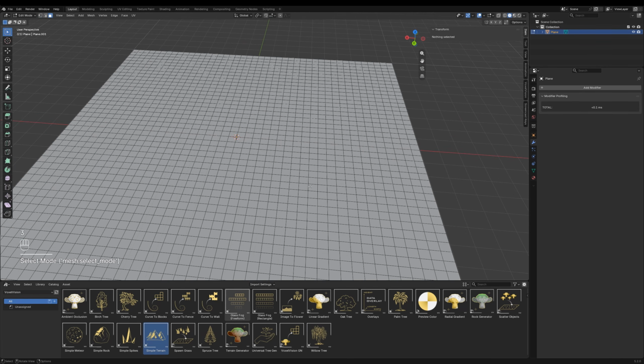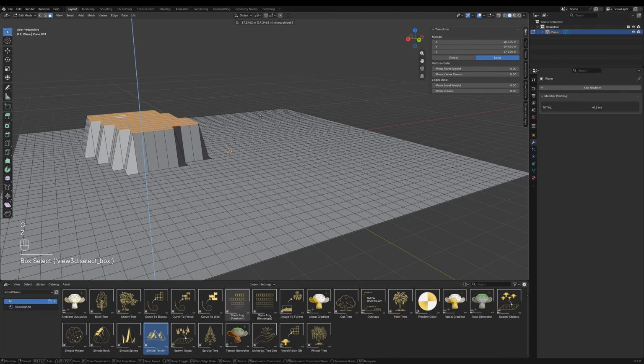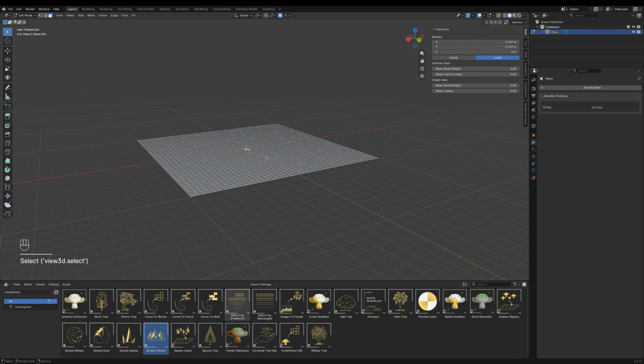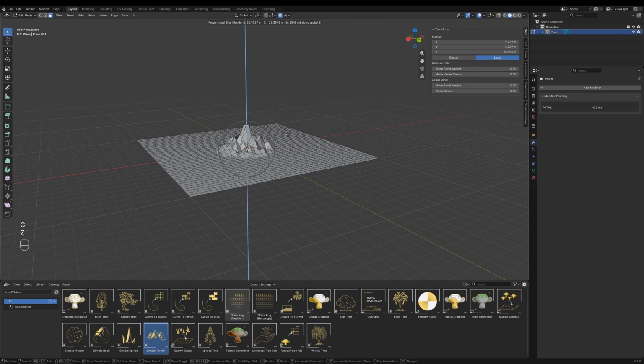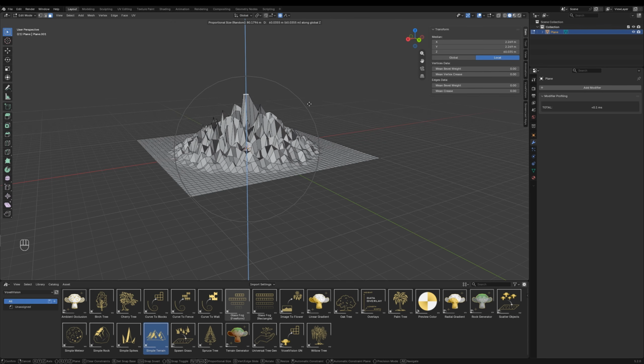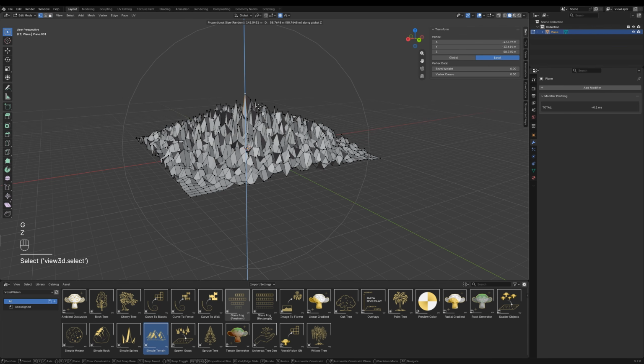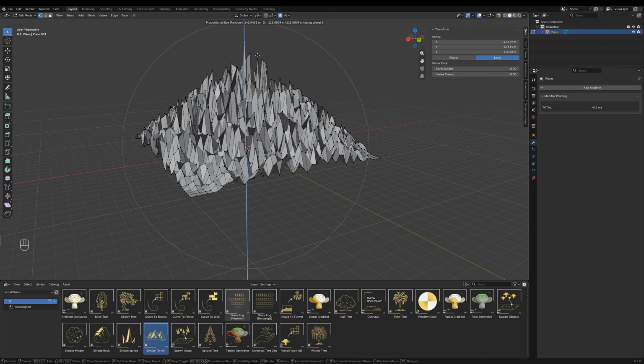So for example, you can go into edit mode and choose some faces, and you could either drag them up like this, or you can work with the proportional editing tool on this button right here. You can also enable and disable it by pressing O, and then you can choose different falloff modes. For example, if you choose random and scroll with your mouse wheel, you can see you get something. Some random faces or points will basically rise up as well, which could build up your terrain.